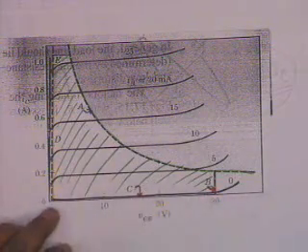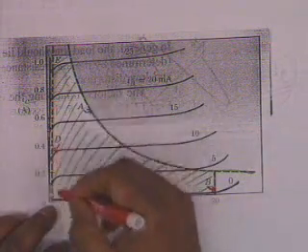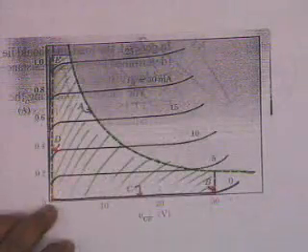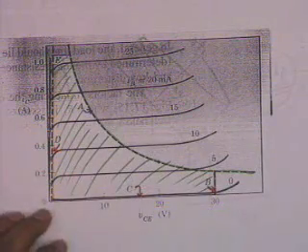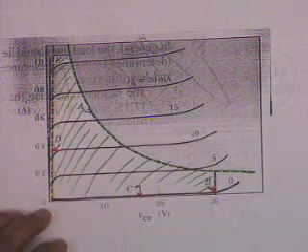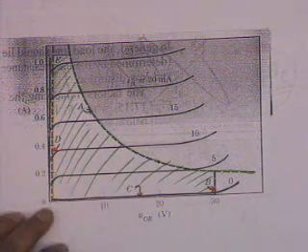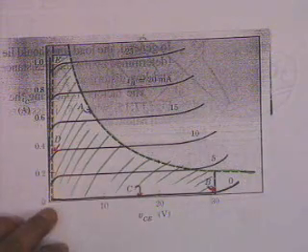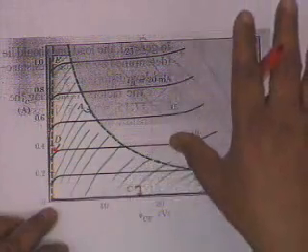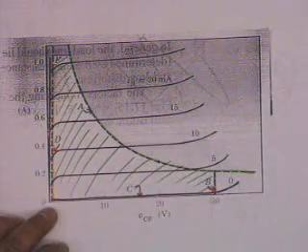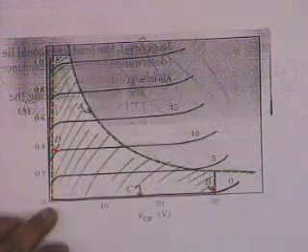And the fourth line, the line D, is this line, this is the saturation line. You cannot make VCE less than this, because then it's a highly non-linear region. Alright, you cannot go beyond this. And another reason is that if VCE is so small, then the collector base junction refuses to remain in the reverse bias condition. It becomes forward biased. And this is why this is called the saturation region.